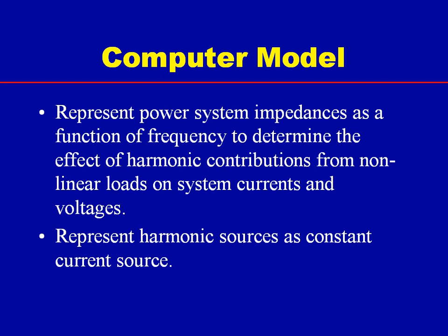As with our manual calculations, the computer model represents the system impedance as a function of frequency to determine the effects of nonlinear loads on the system currents and voltages. The nonlinear loads are represented as constant current harmonic sources.